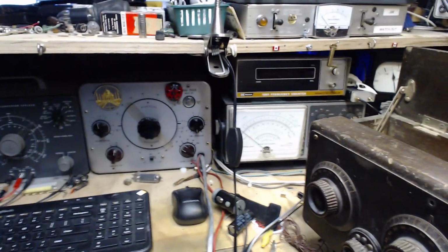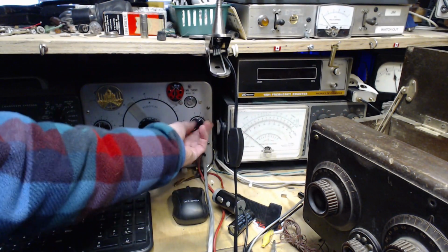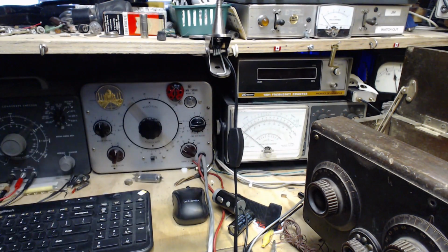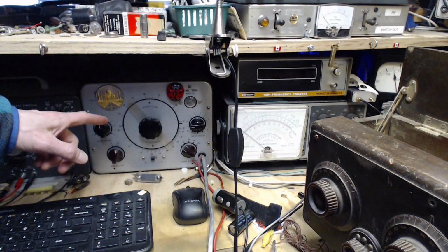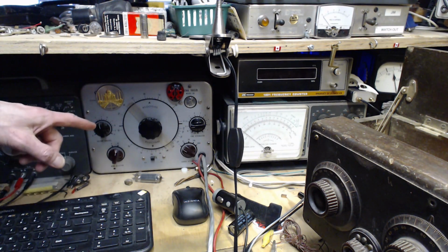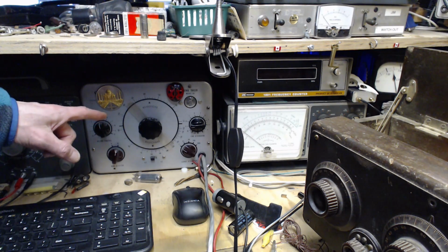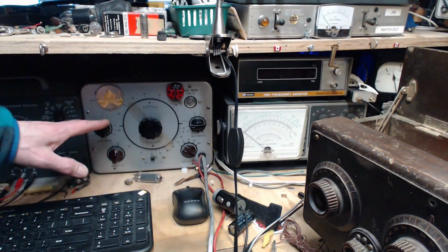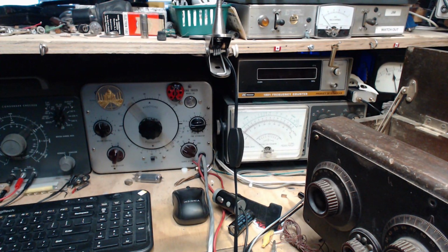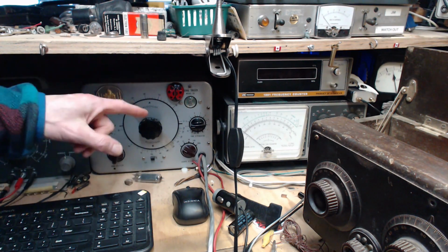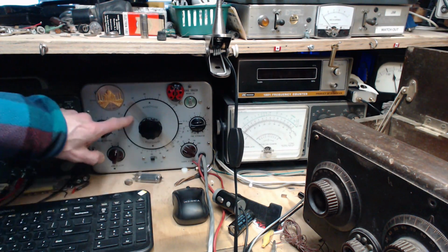Okay, let's get the signal tracer going here. So this guy hums a little bit. I think that's kind of normal for it. This is a radio, but it's not a typical radio. This is a TRF radio, the same as this old one here, which means it has no local oscillator, no converter in it, no intermediate frequency stages at all. It's just straight from the antenna through amplifiers, detector, and then out the speaker. There's a speaker in here.